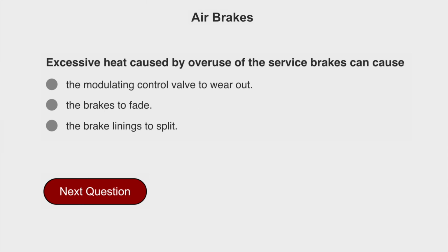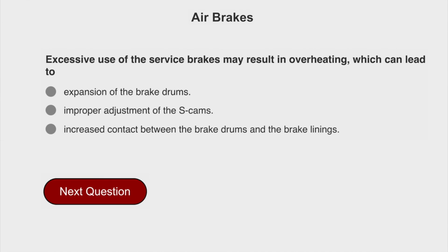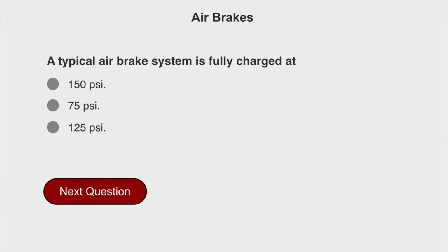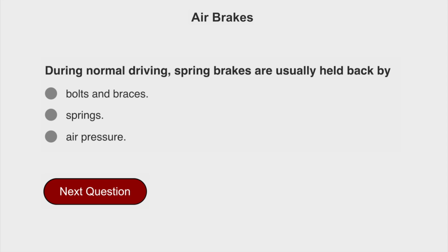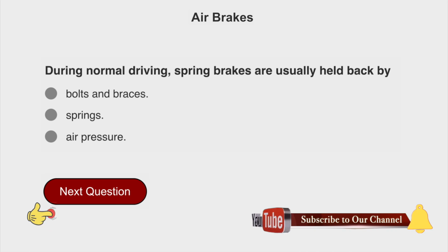Excessive heat caused by overuse of the service brakes can cause the brakes to fade. Excessive use of the service brakes may result in overheating, which can lead to expansion of the brake drums. A typical air brake system is fully charged at 125 psi. During normal driving, spring brakes are usually held back by air pressure.